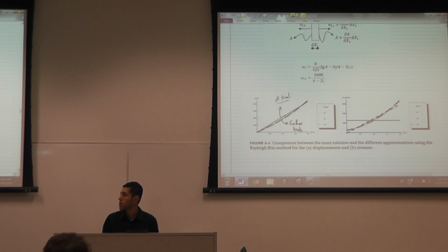What's the order of the strain? The strain is constant, because the strain is the first derivative of the displacement. The strain is constant, and the stress is a linear function of the strain, so the stress is constant. And so you get constant stress. Now, I will remind you of this again when we plot the stresses on elements and we find constant stresses on elements. So the stress here is constant.